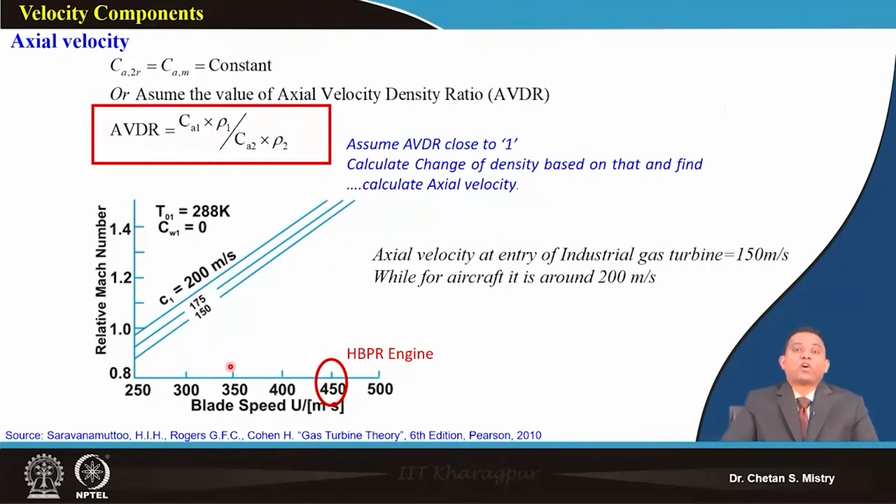So the selection of the parameter called flow coefficient comes into the picture when we are deciding this. When we are not aware of which parameters are known to me, say my mass flow rate is unknown, I don't know my peripheral speed, I don't know my axial speed, under that condition you can safely assume the flow coefficient in a particular range, as we have discussed, and then after that you can start doing your design. Okay, so there are strategies for the selection of this parameter.